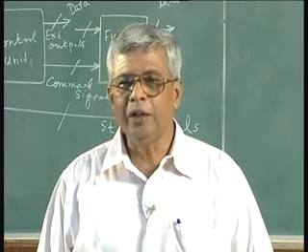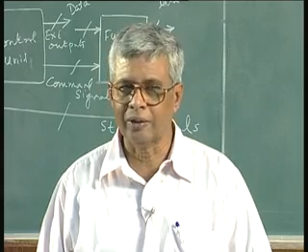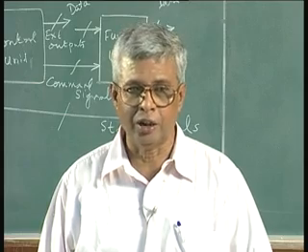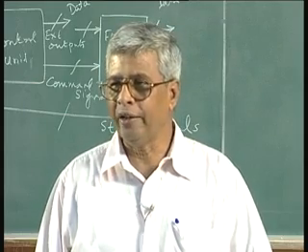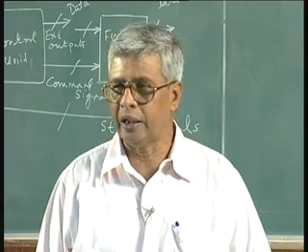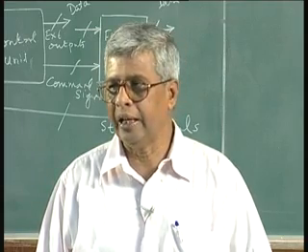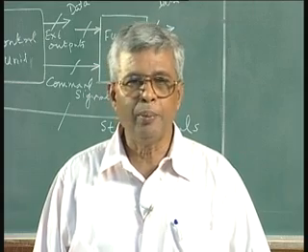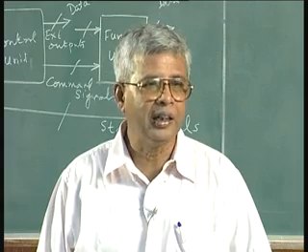A and B and full adder is a combination circuit. I have been maintaining this, right? It is not a sequential circuit, unless it is a serial adder, 1 bit adder, which we are not talking about here. We are talking about parallel adders. When you say 4 bit full adder, you mean 4 bits are given as A, 4 bits are given as B, and sum 4 bits and carry 1 bit, 5 bits come as output, assuming ideal components immediately, practical components after delay depending on the gate structure.